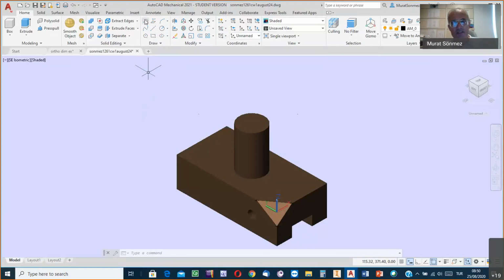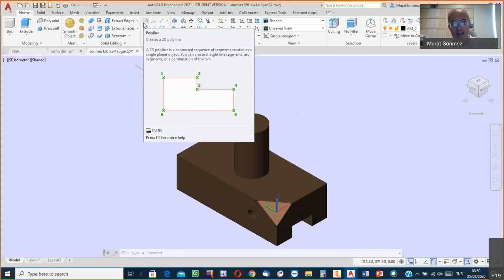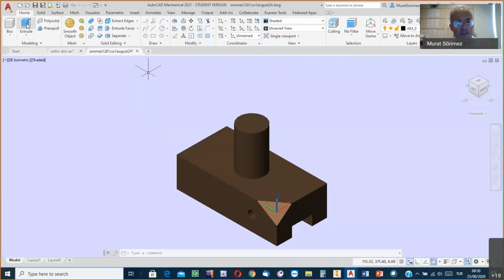If you created the boundary lines for having a closed area using the polyline facility, then the area bounded by the segments of the polyline is going to be automatically recognized as a region. Yes, it must be a region in AutoCAD for creating the model of something. If you apply the extrusion process, then it is going to be a right prism.